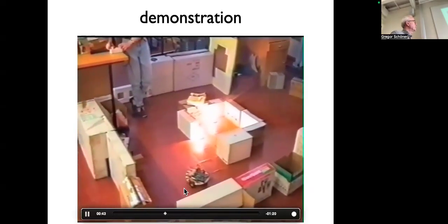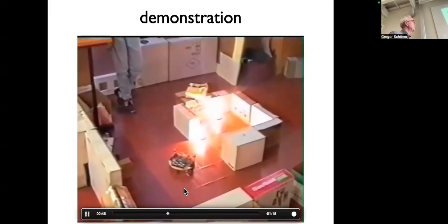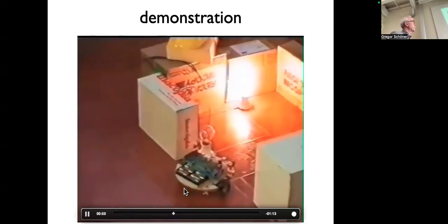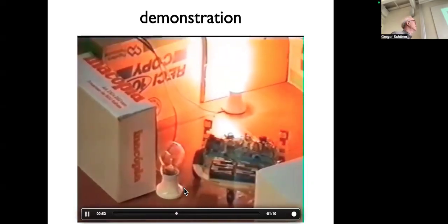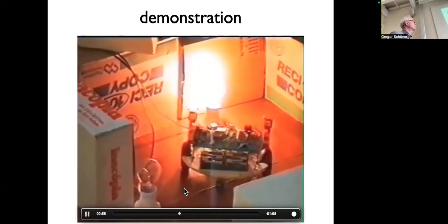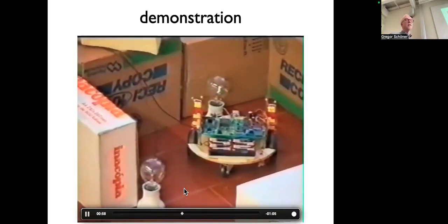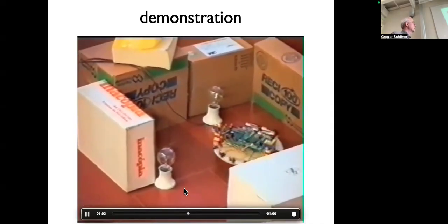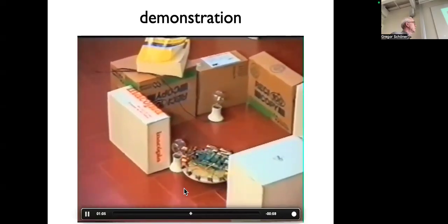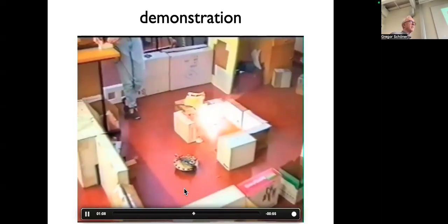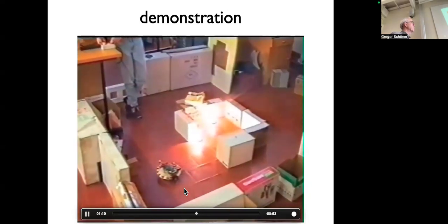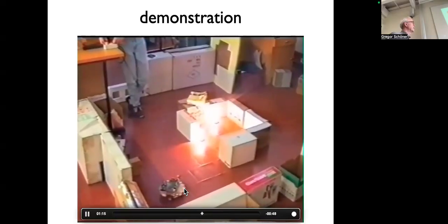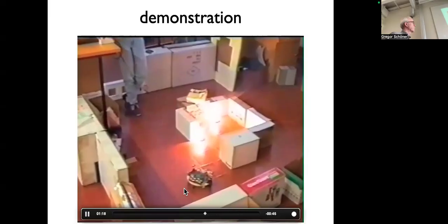Here you see now it does suddenly pick up that difference and goes there. We also controlled the speed. The higher the light intensity, the slower the speed. That's why it stops. And therefore we could make it go to that other light source and stop. And this is really sometimes called phototaxis. And then it oscillates a little bit because now there's no source, and it finds its way out again. Kind of cool, right? And then it takes some time, so far the sensors point in the wrong direction, but now one of the sensors really gets some input and, well, isn't that cool?